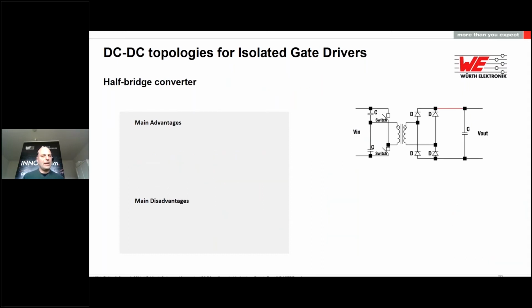The half bridge, like push-pull, is based on a forward converter topology, therefore it is simple to design. The transformer does not need to store the energy, so it can be smaller in size. Also, there are fewer windings than a push-pull, therefore it is simpler with less parasitic interwinding capacitance. Low component count, similar to push-pull, but note the difference that one of the primary switches is now on the high side, so it needs a bootstrap voltage. Again, no snubber is required and efficiency ranges around 85 to 92%.